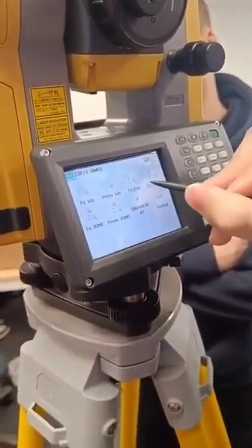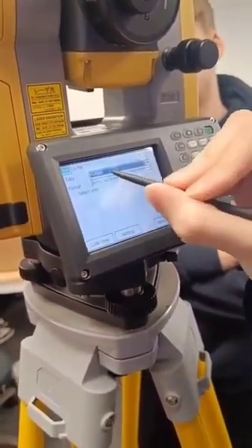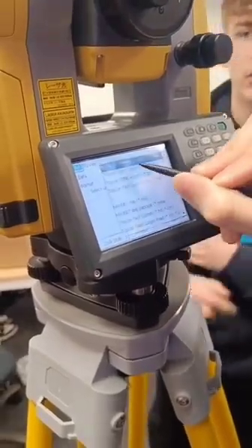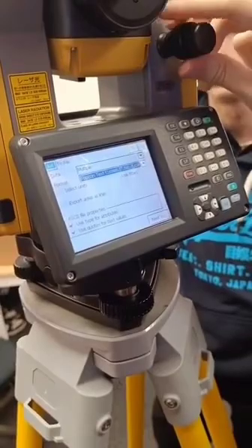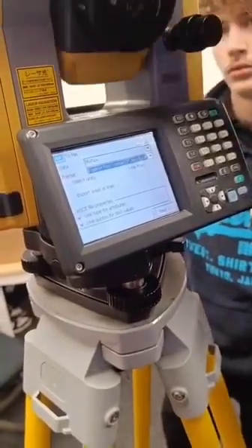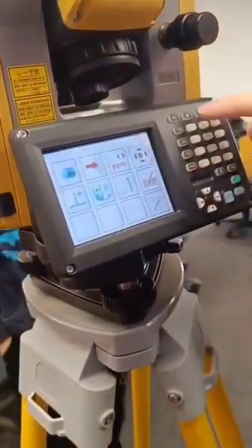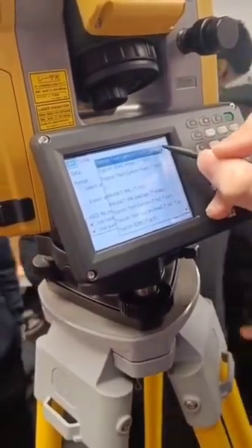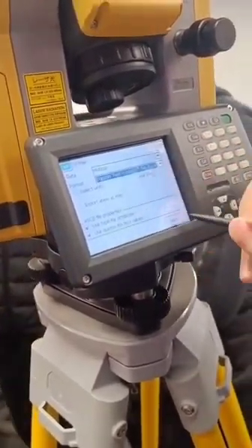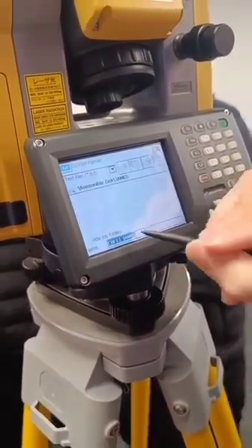You also need to do a CSV file. So I'm just going to go back in here, AutoCAD drawing, change it to top context custom. I'll just turn the laser off real quick, so it's not in the way. So top context custom, that's the one you want to choose, .csv. And then you don't need to change anything in here.